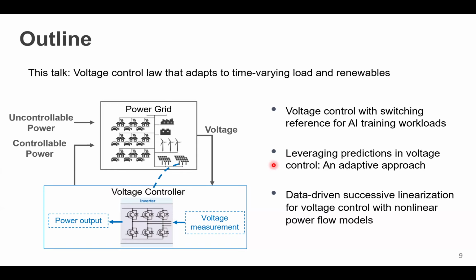Yeah. As far as it looks, in Virginia's data center alley, there are some data centers that connect to the distribution system. Whether their very large computing load can scale to this level needs to be further checked. But even if it's not hundreds of megawatts, if it is tens of megawatts connected to the distribution system, that can still cause voltage issues and voltage fluctuations. That's a very important question.